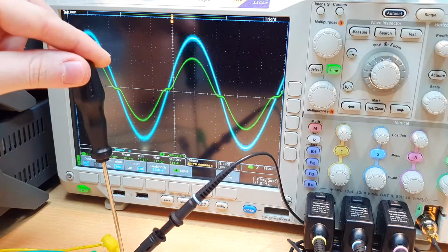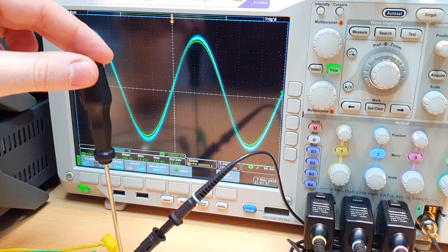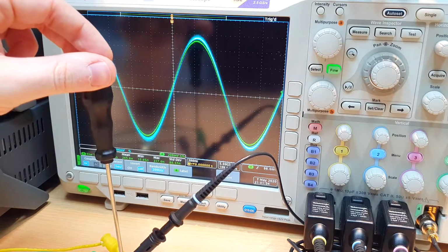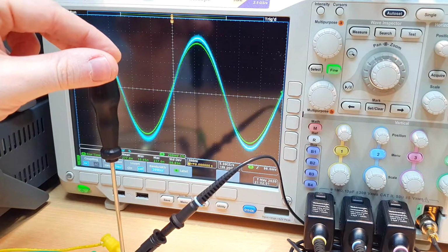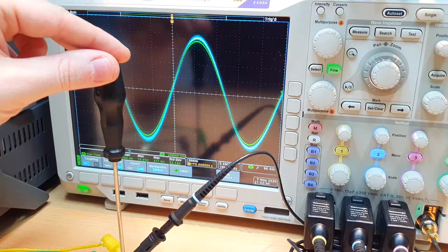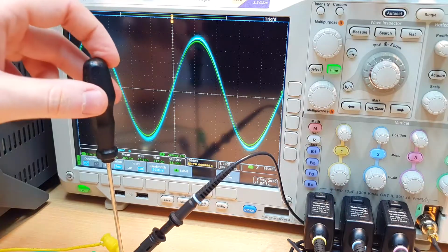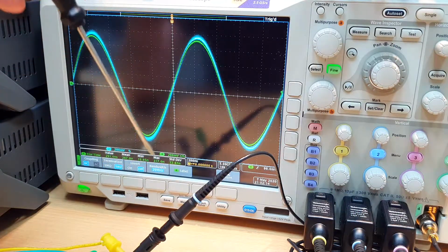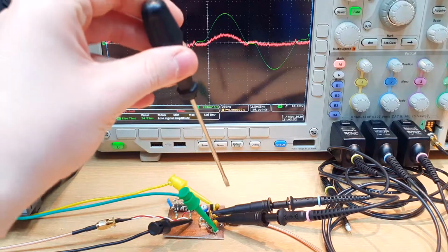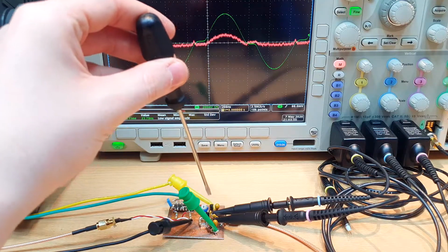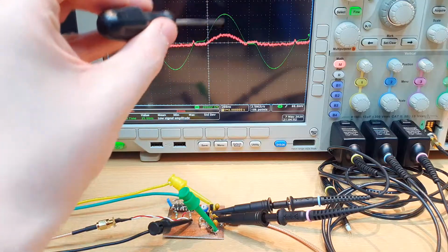Look at this. Very interesting. If I continue to increase, we will start to go to class A operation. Here we are in class AB. If I continue to increase, we're going to go to class A operation, and we won't see any difference on the scope, but we can probe the current on the transistor and see the transition between class AB and class A. Now we are using two probes to make a differential probing on the output resistor of the NPN transistor, so we can see the current waveform on the transistor.